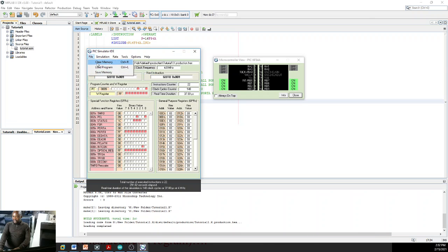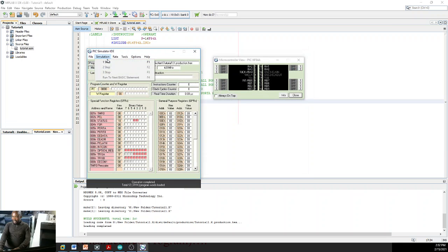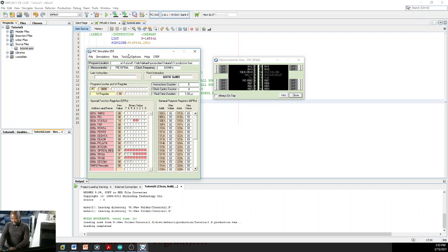Let's stop the execution, reload the program, and then start execution. This time around, FF will be written to port A and 0 will be written to port B. So let's start. Now we go to bank 1, bit set file, move 0 into trace A, make these outputs, clear file, trace B, make those outputs, go to bank 0, clear bit 5 of the status register, clear port B to make the port B pins off, and now move FF into W, move that to port A.